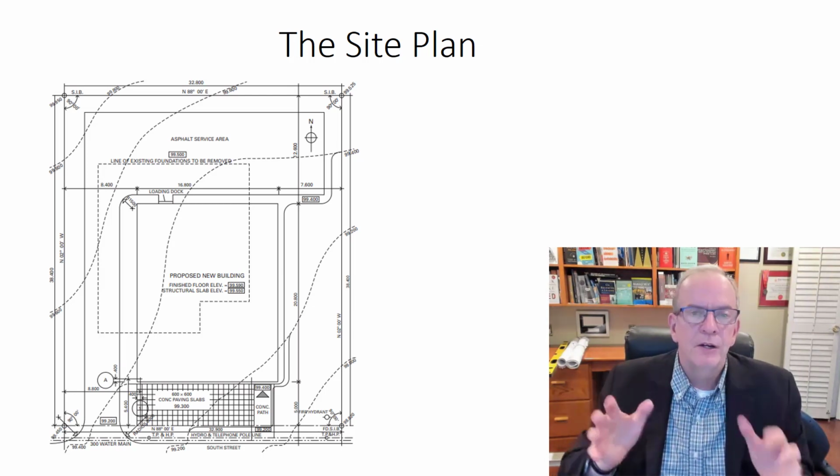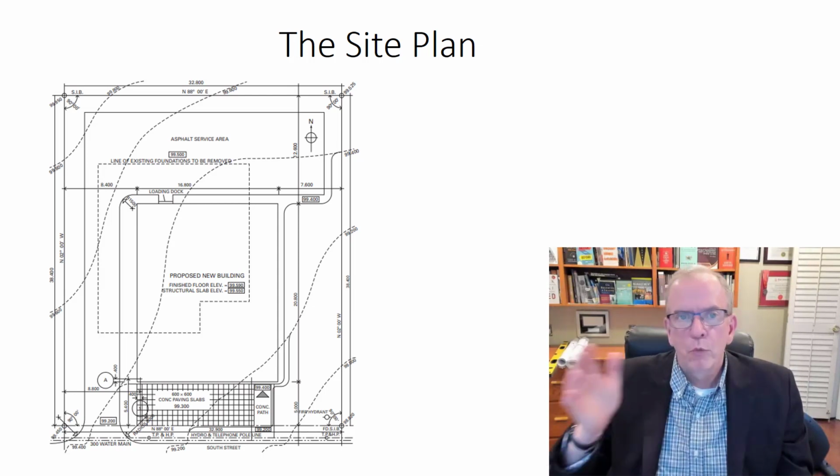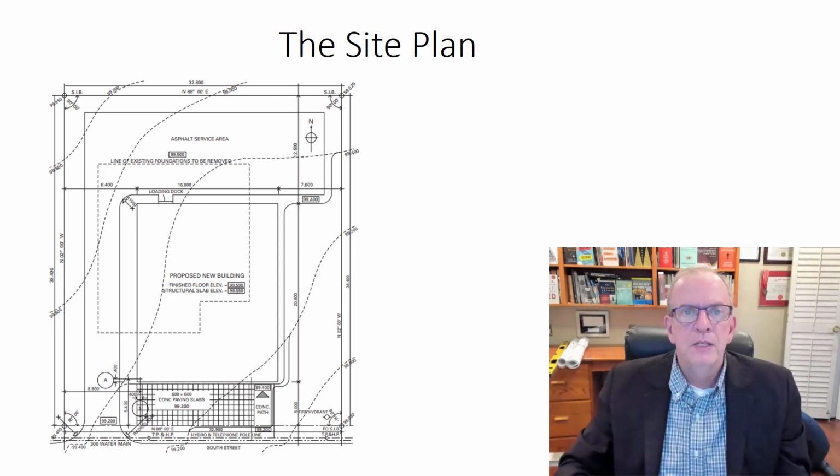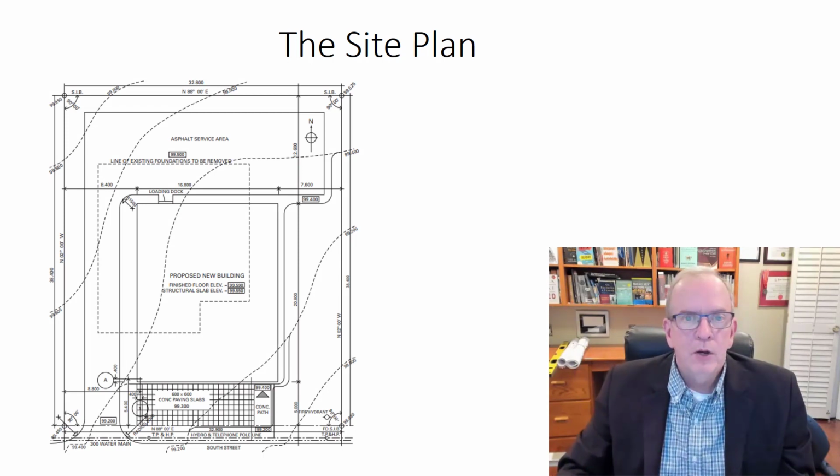If there's a fire, you know, it may hop from one building to another. So where are the openings? How big can the openings be? Can there be any openings depending on how close the building is to the property line? So there's a lot of requirements that come into play there, and more that we'll discuss in these series.